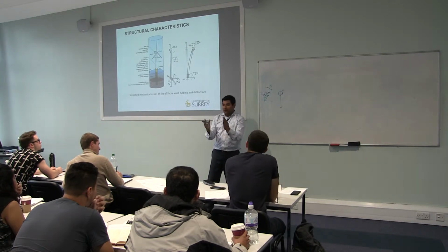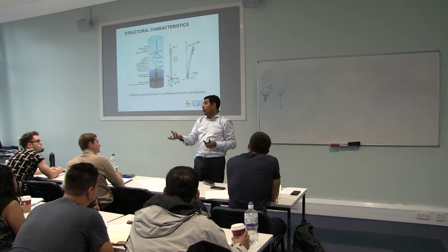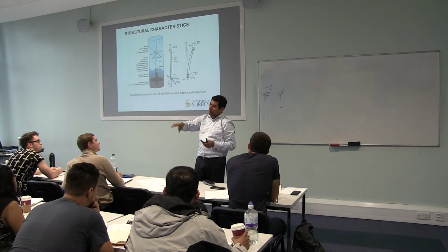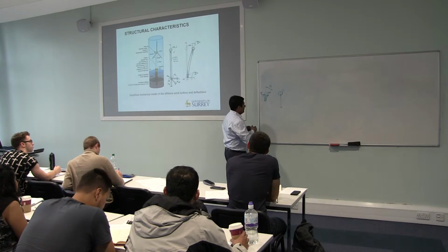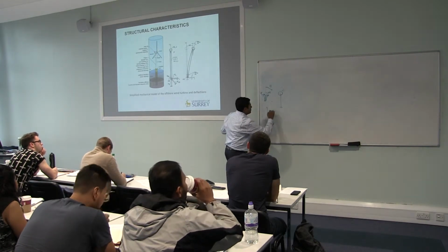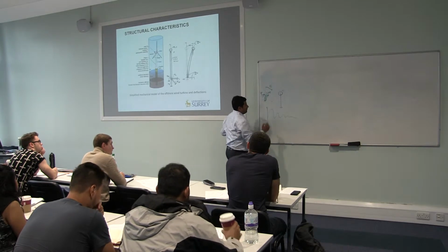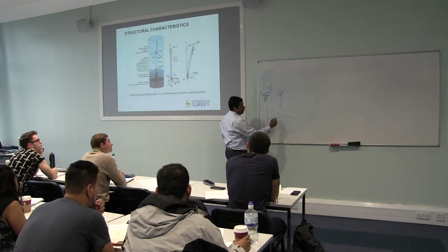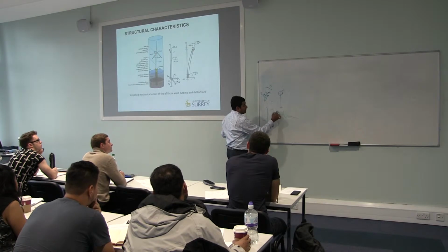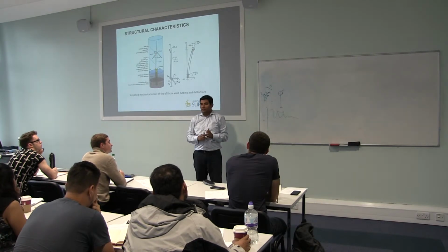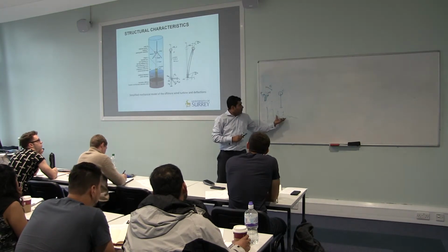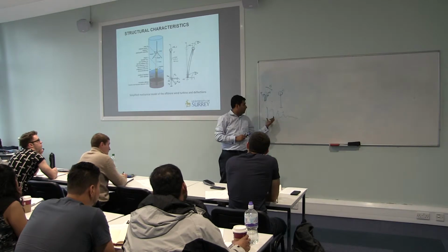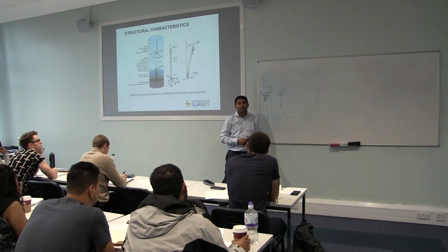It's like you take a ball in water and you push it down and see how it bobs. Once you take the load off, it will bob and come to a standstill. So once you take the load off, that will give you the natural frequency. If it takes a longer time to decay, low damping; faster decay, high damping.